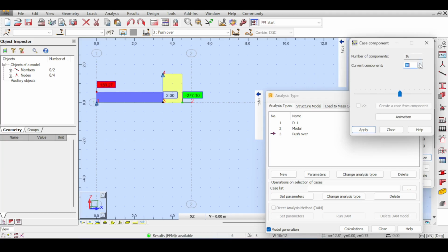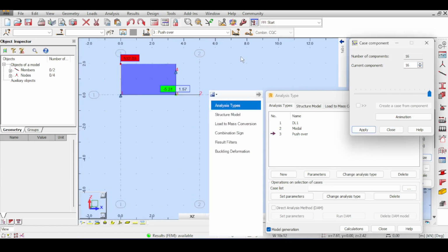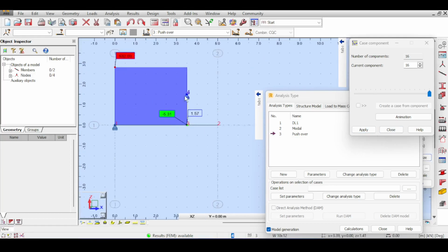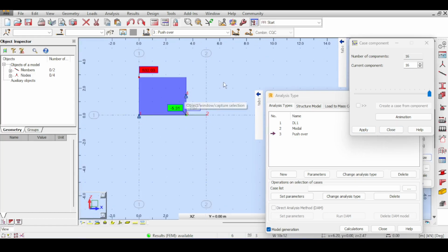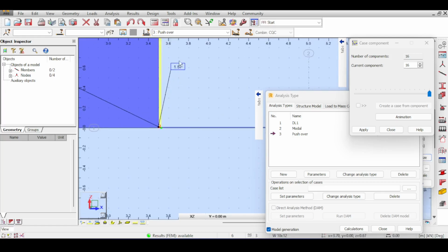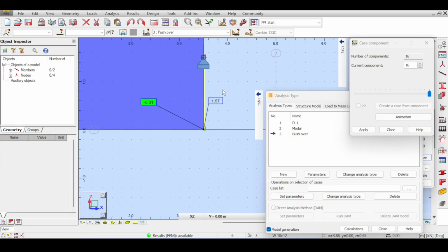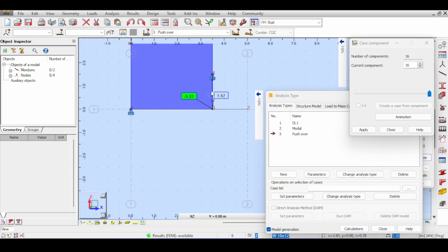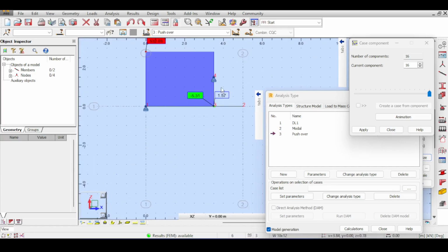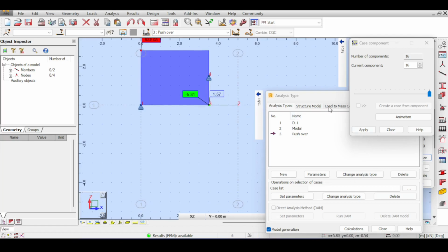Let's click. So it's increasing linearly as we are expecting, and suddenly it snaps, right? Yeah, it snapped here. It snapped at around 415 kilonewtons. So I think it snapped, and this is perfect proof of that. Now, what still remains a mystery for me is why this is not unstable. I think you still see some sort of residual force here that Robot couldn't shake, and that's the reason why this is still stable, because theoretically speaking you have a small force here, and this small force seems to keep it stable.